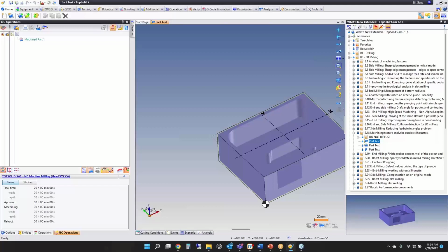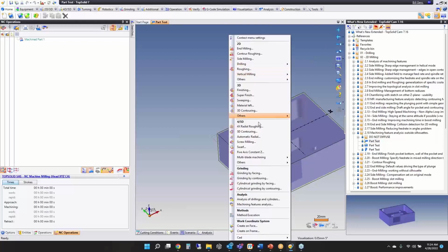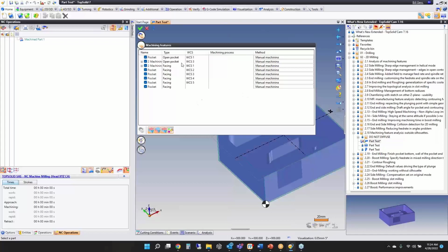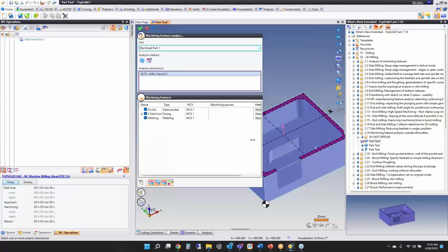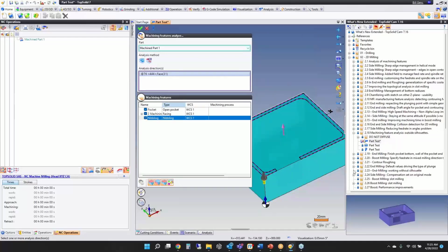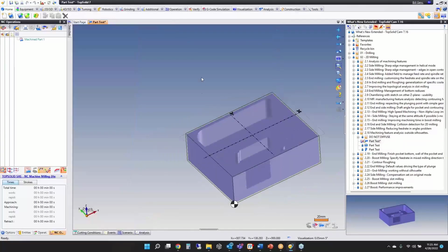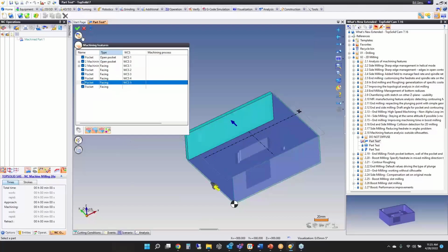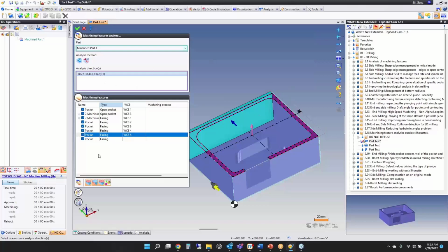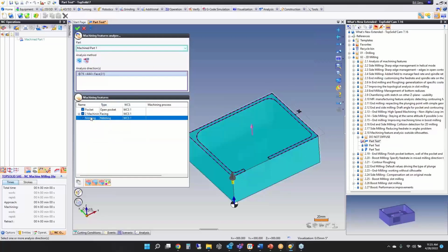Now, next one. Again, this just has to do with machining feature analysis to find outside silhouettes. So if we go to machining feature analysis, as long as you have a direction reference, meaning we want to focus the area based on that direction, and refilter, then you're going to get the nibbling profile or the outside profile of the part that you can apply a methodology to. If you don't do that, and I should have started there, minimize this so we can see more. Go back to here. Because right now I'm on a 5-axis machine, so it can technically see machining on all sides of the part, right? This is why we added the improvement to say, only based on this direction, do the analysis, and then it gives you that nibbling profile.